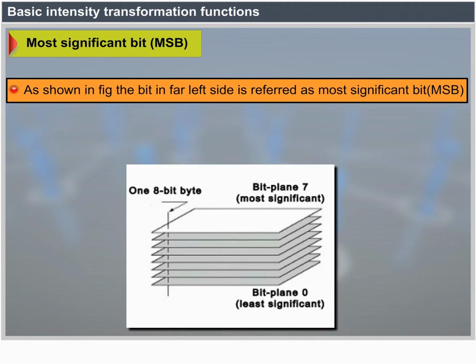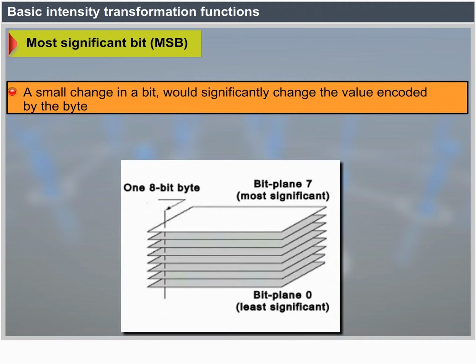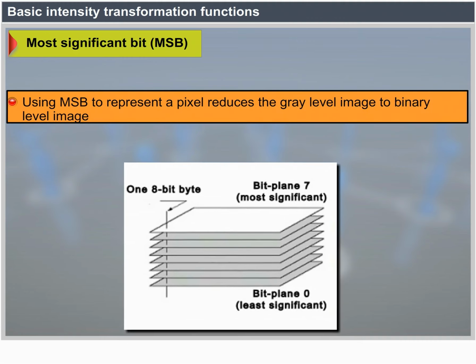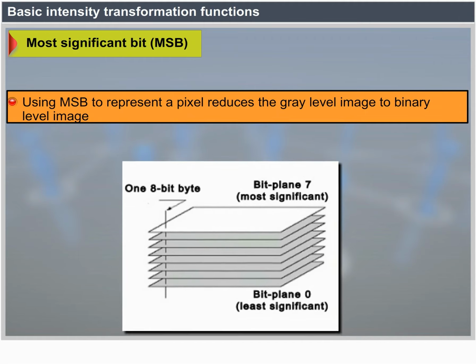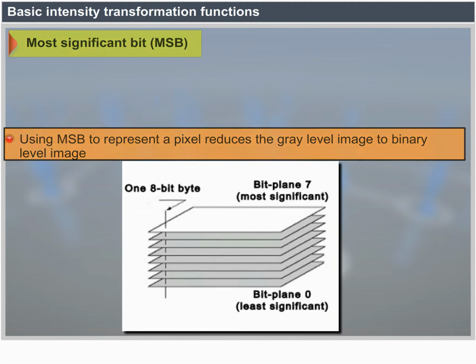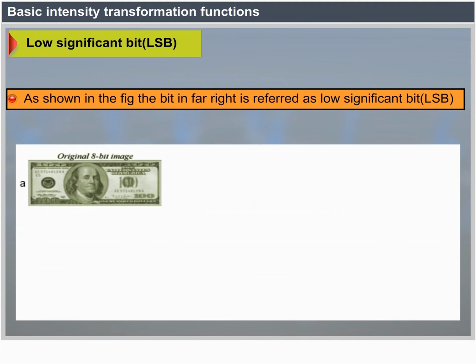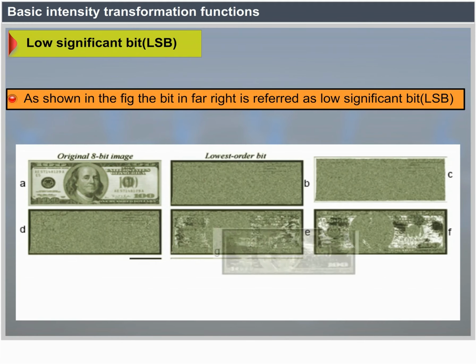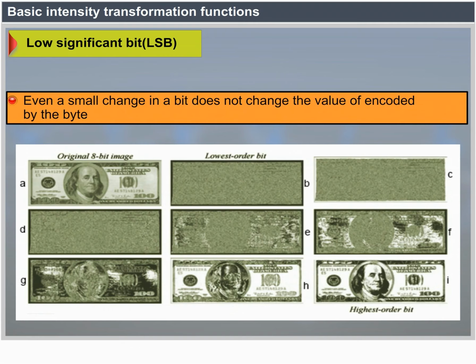Some properties of the 2D discrete Fourier transform. Relationships between spatial and frequency domains. If delta t and delta z are the separations between samples, the separations between the corresponding discrete frequency domain variables are delta u equals 1 by M delta t and delta v equals 1 by N delta z.